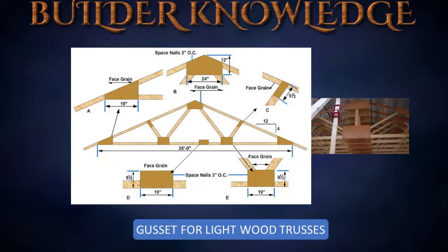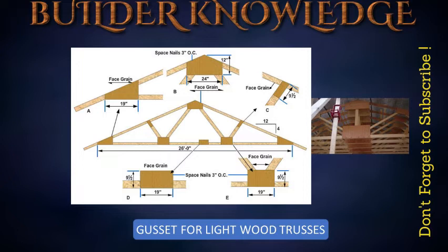Plywood gusset king post trusses are limited to spans of 26 feet or less, if spaced 24 inches apart, and fabricated with 2 by 4 inch members and a 4/12 roof cut. The spans are somewhat less than allowed for W trusses having the same sized members. The shorter span for king post truss is due in part to the unsupported upper chord. On the other hand, because it has more members than the king post truss, and distances between connections are shorter, the W truss can span up to 32 feet without intermediate support, and its members can be made of lower grade lumber.